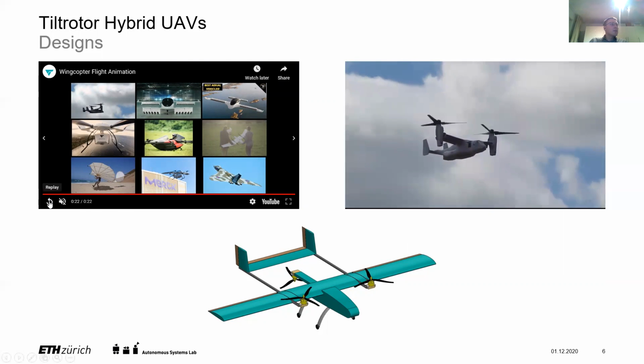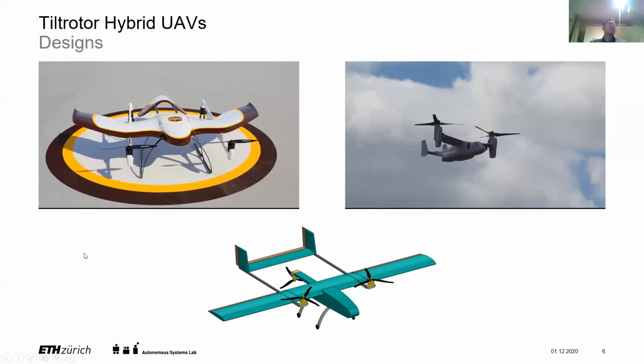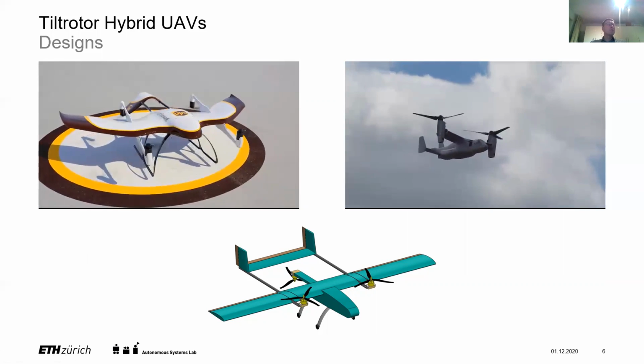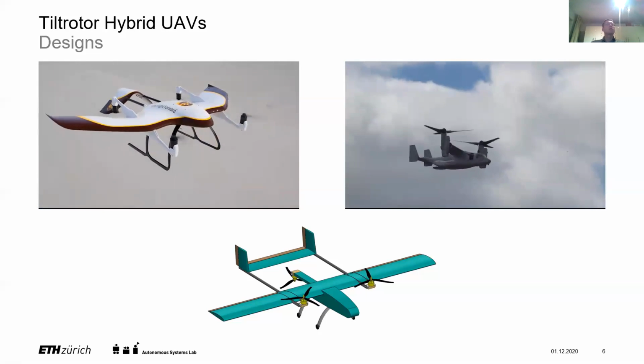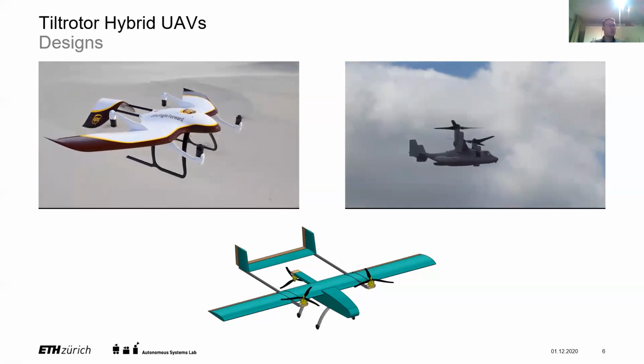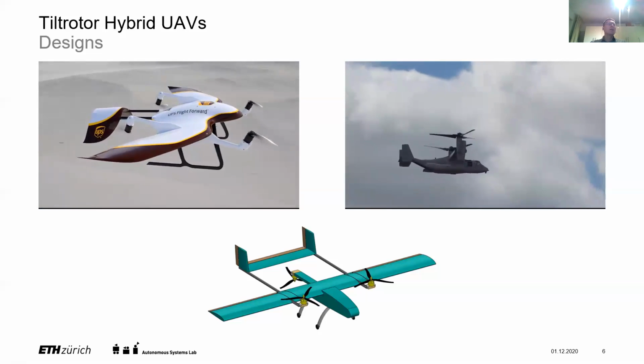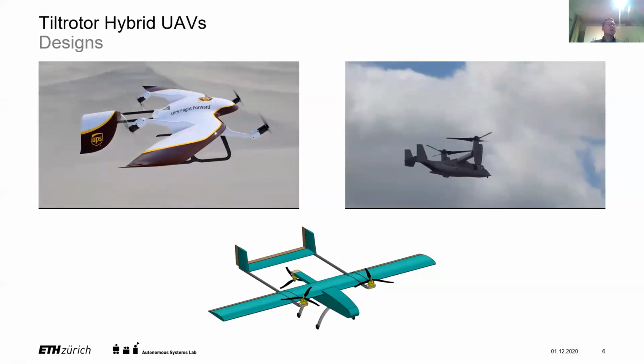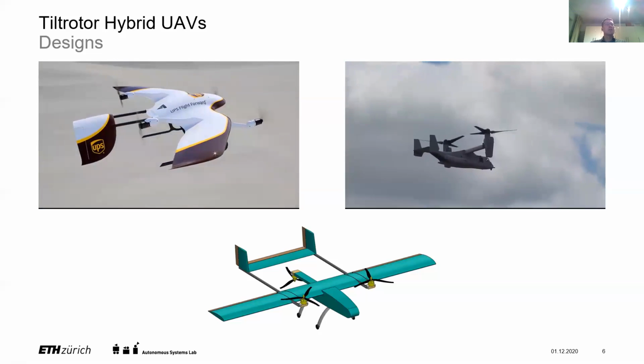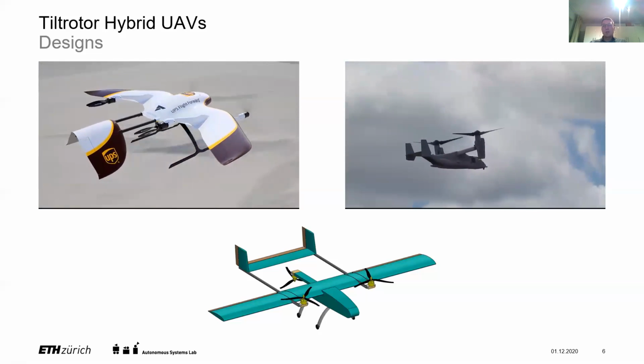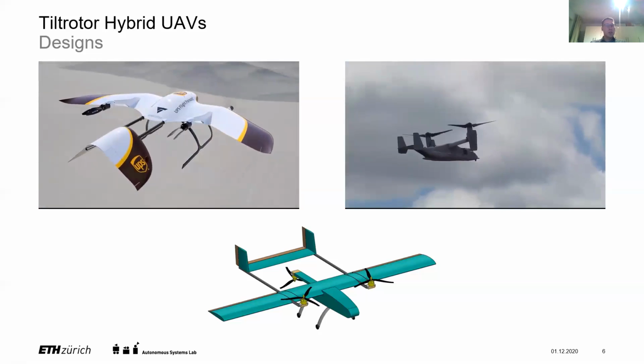This can be really well seen here on the left. So we see how the propellers initially are in a rotor wing configuration. So the thrust generation is vertical for takeoff. And then once we transition, we move the propellers forward until the thrust is longitudinal, and basically the lift is now generated by the main wing.